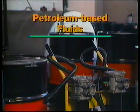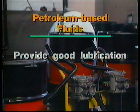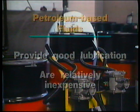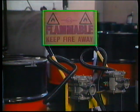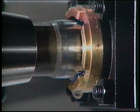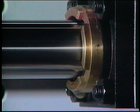Petroleum-based fluids have become the fluid of choice in most industrial hydraulic systems. They provide good lubrication and they are relatively inexpensive to use. However, they can be a fire hazard. If the oil gets out of the system, it can encounter temperatures hot enough to cause it to ignite.